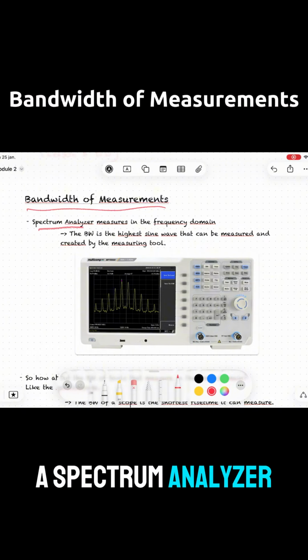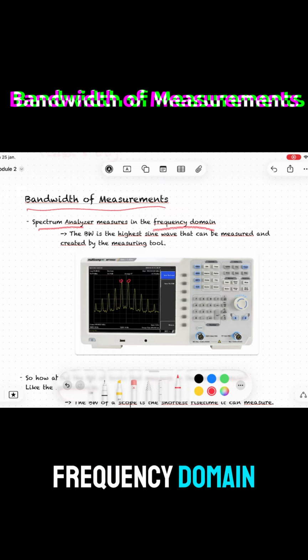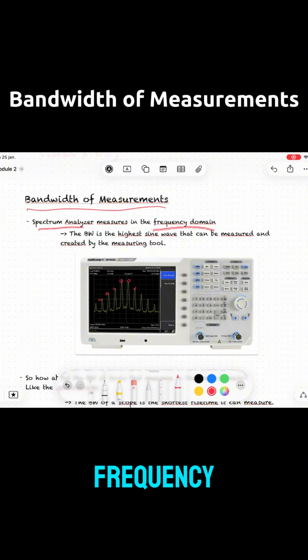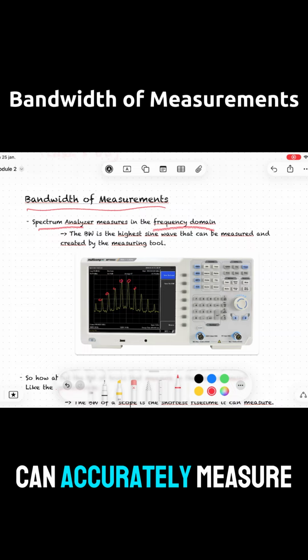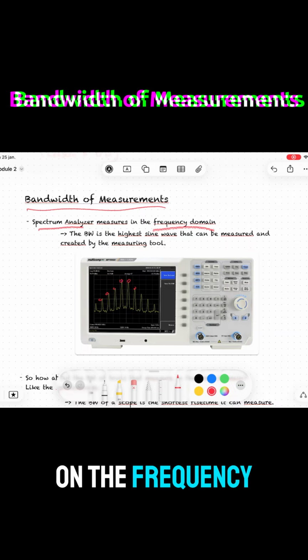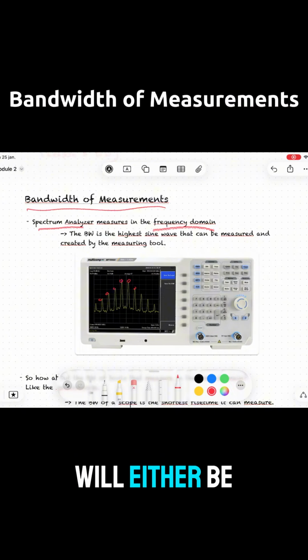A spectrum analyzer measures signals in the frequency domain. For a spectrum analyzer, bandwidth means the highest sine wave frequency that the instrument can accurately measure and represent. In other words, the bandwidth sets the upper limit on the frequency content that the instrument can see. Anything above that limit will either be heavily attenuated or not measured correctly.